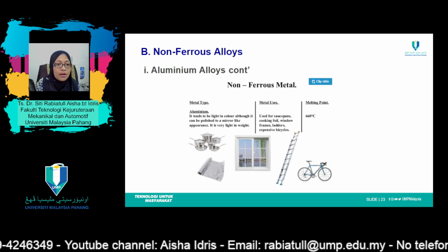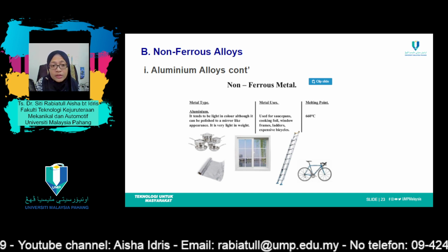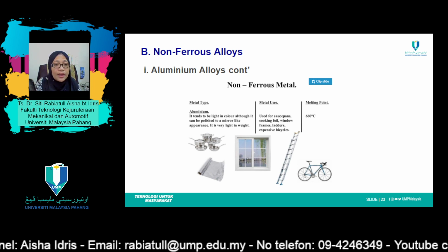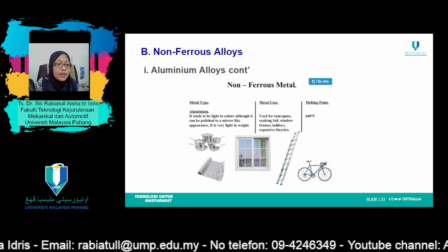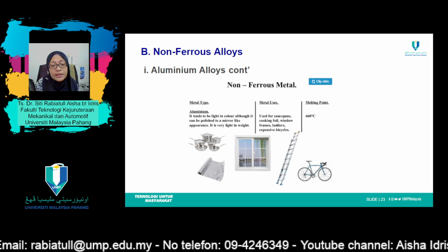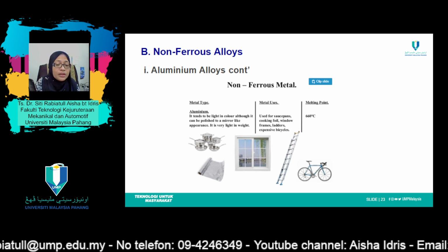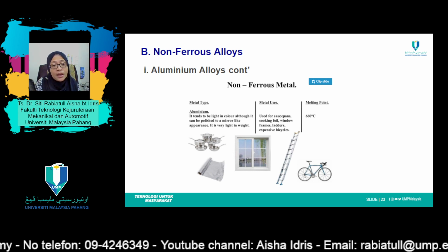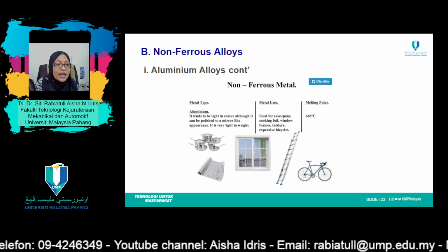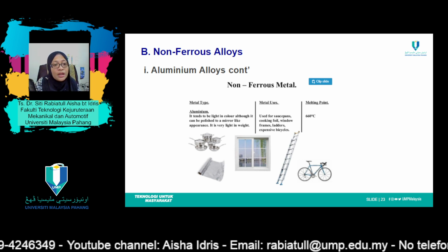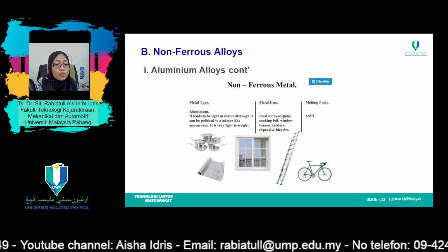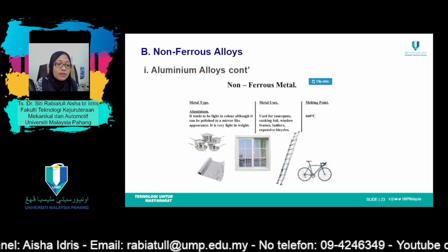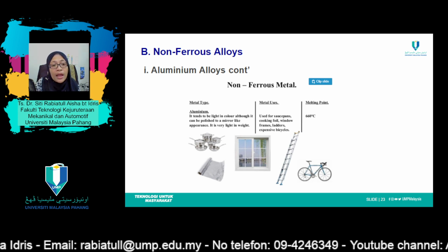Generally, aluminium alloys are classified as either cast or wrought. Composition for both types is designated by 4-digit numbers that indicate the principal impurities and in some cases the purity level. For cast alloys, a decimal point is located between the last 2 digits. After these digits is a hyphen, and the basic temper designation, which is a letter and possibly a 1 to 3 digit number, indicates the mechanical or heat treatment to which the alloy has been subjected.